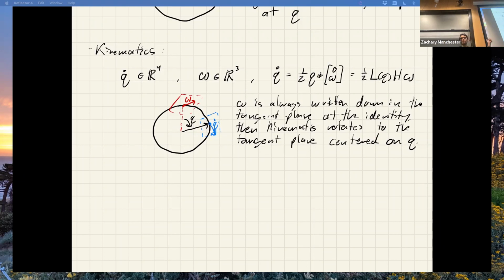So literally, there are only 3 degrees of freedom, right? But it's this unit sphere thing. So if I were to try to write it down with only 3 coordinates, i.e. Euler angles, which are like latitude and longitude, what I'm really trying to do there is unroll the sphere onto, like the globe analogy, right? Latitude and longitude on a globe, which is easier to think about. I can write it down using 3 vectors to be on the surface of the sphere. Or if I'm using latitude and longitude, what I'm implicitly doing there is trying to unroll the globe and write it down on some flat 2D plane with X and Y axes equal to latitude and longitude, right? That's what I'm trying to do. And that has to break somewhere. There's no way to do it globally.